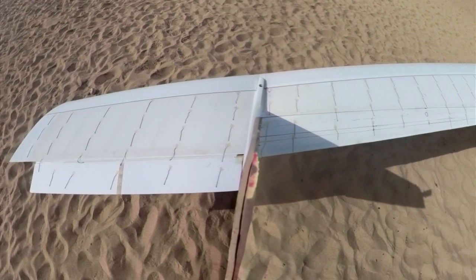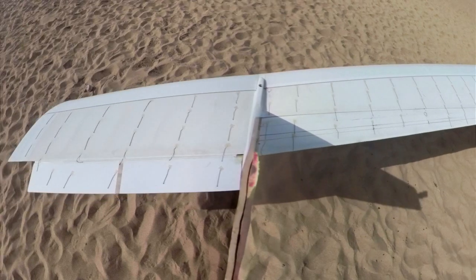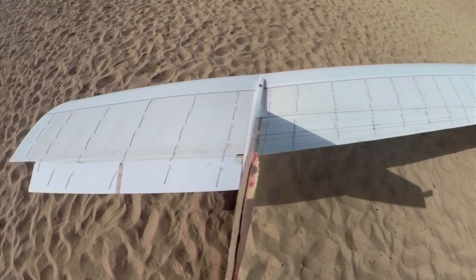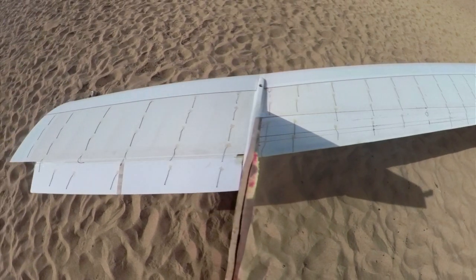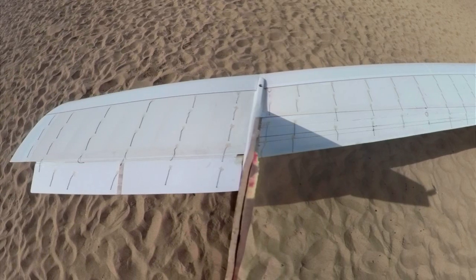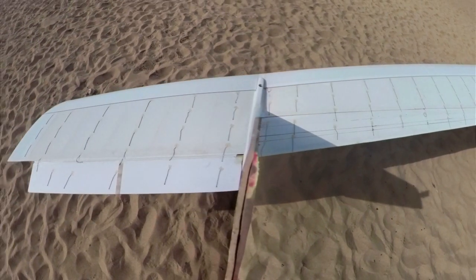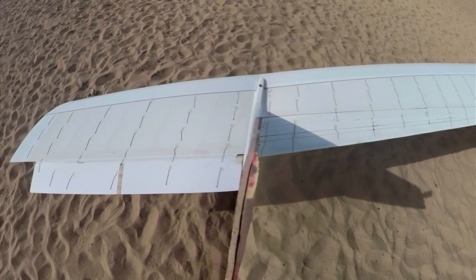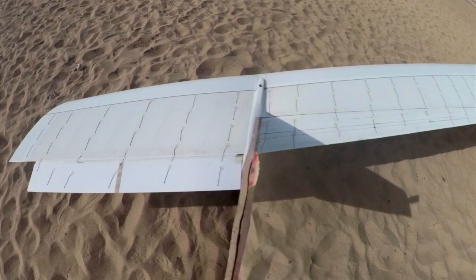I think you'll see me trot forward here a little bit, maybe. There's a lot of down Elevon there, and the inboard 2/3 of that Elevon addition, the flow's just fine. That's deflected down way more than 15 degrees, and the flow's attached. So at this point, I think, problem solved. Everything looks really good over the wing. So it should be quite manageable.